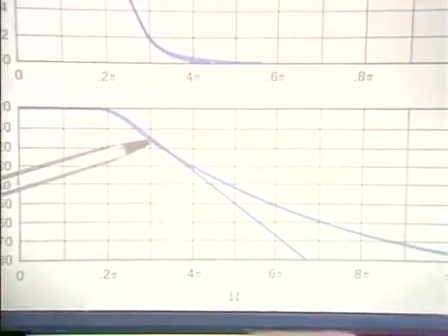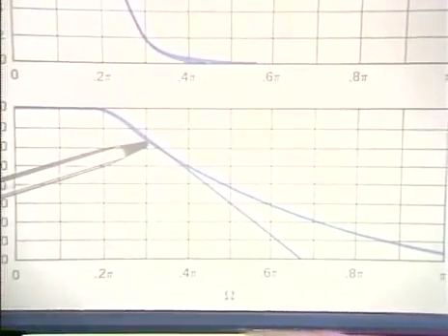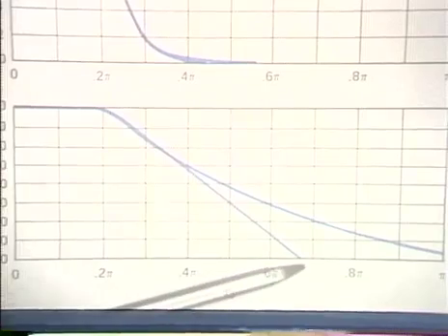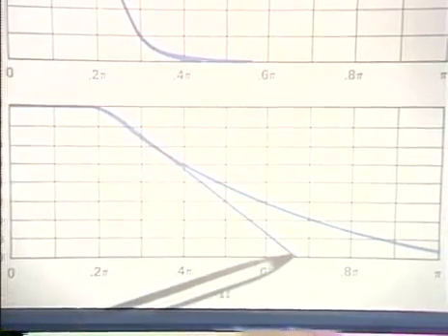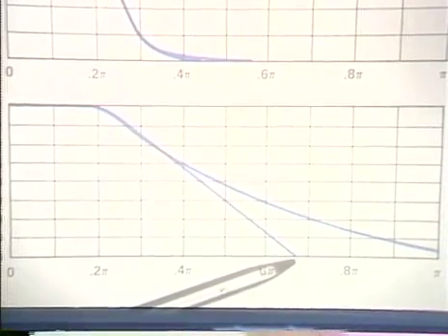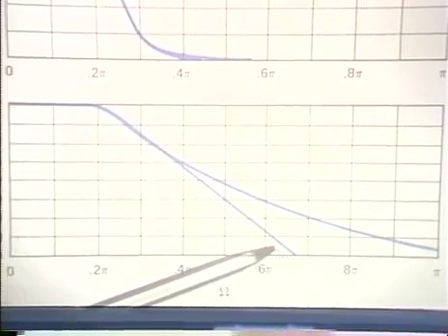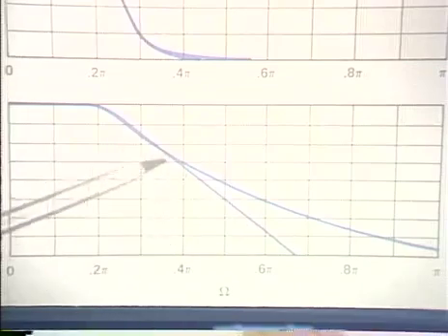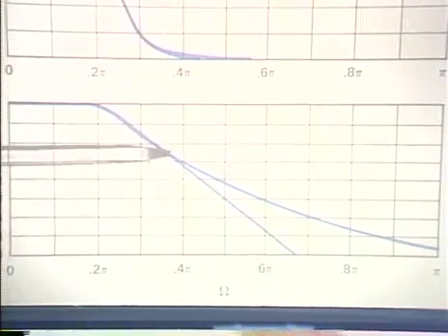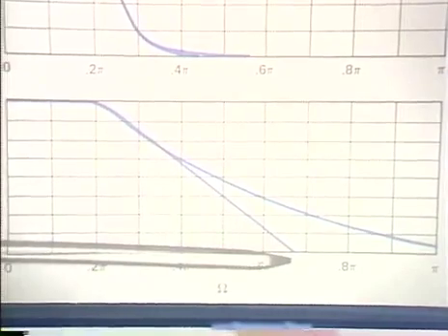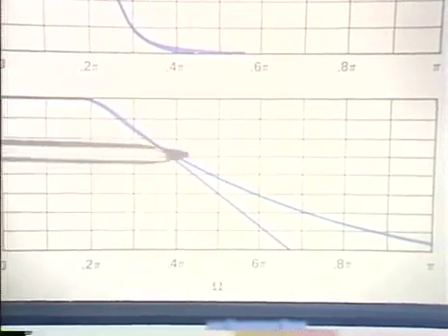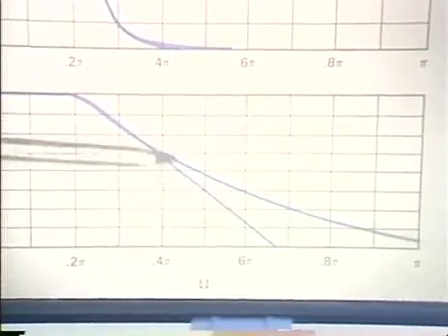And notice, in fact, something very interesting, which is that the filter that we obtained by mapping the Butterworth filter to a digital filter through the bilinear transformation, in fact, falls off in frequency much more rapidly than the one that we got through impulse invariance.